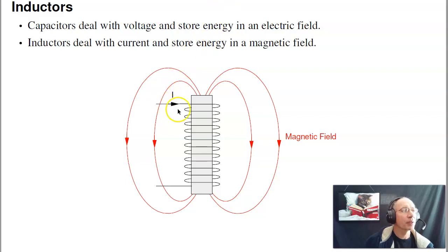Second problem with inductors, it takes a lot of copper, a lot of windings to produce a sizable inductance. A large amount of wire means a large resistance. So inductors also have a large resistance, unlike capacitors. And third, you almost have to use iron in an inductor. Iron has a relative permeability as much as 1,000 times higher than air. By using iron, that makes inductors very heavy.